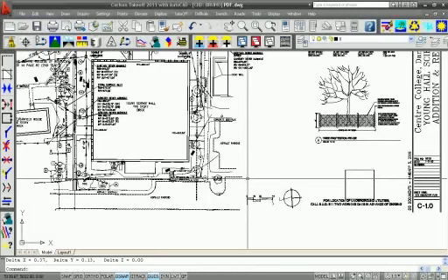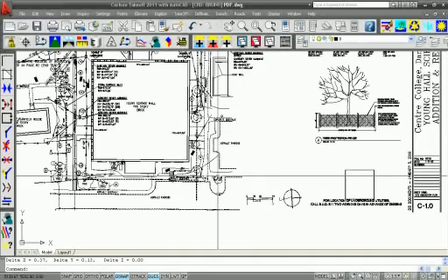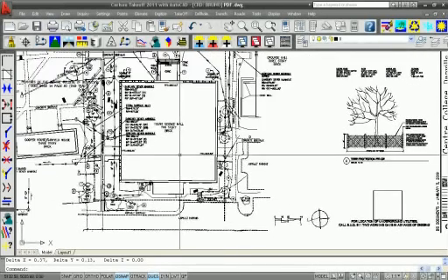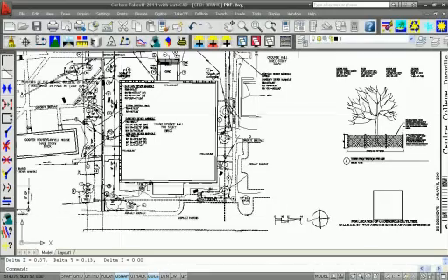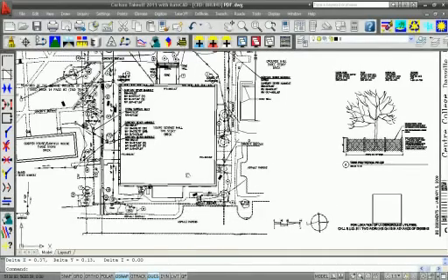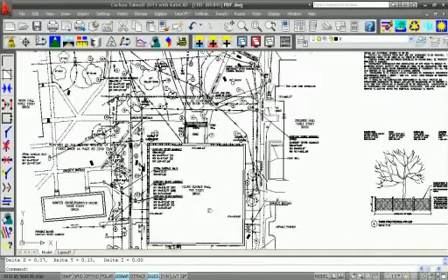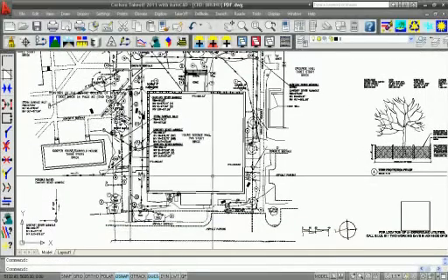Yeah, in terms of workflow, you typically would scale the drawing first. You can bring in a PDF, maybe do a drawing cleanup on it, but one of your first steps should be to scale the PDF so all the line work you create is true. You're not doing that after the fact. Yeah, so this is a step I could have done first when I brought it in, but I got excited with the different layers. Absolutely.